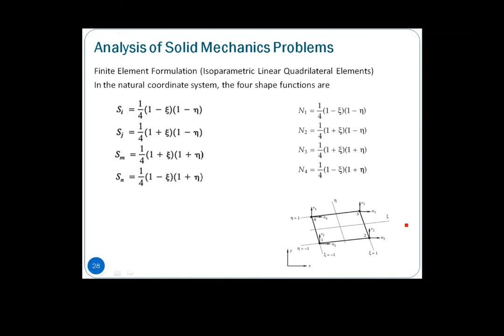Then how it is formulated to determine our stiffness matrix using what we call the energy methods. So here we have a 6 times 6 matrix under CST or linear triangular elements. Now under the quadratic triangular element or LST, we have a 12 times 12 matrix. If you are looking into linear quadrilateral elements, it is also the same.